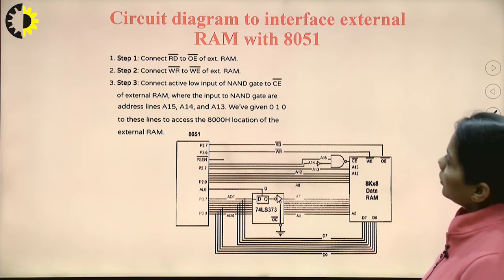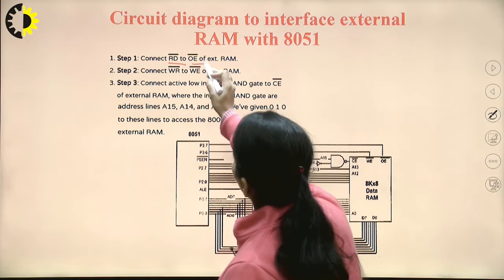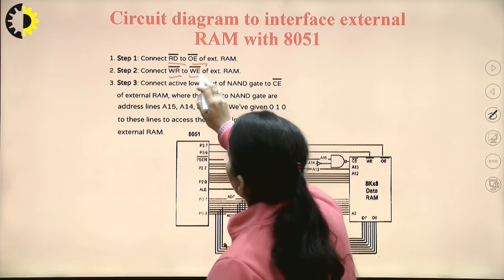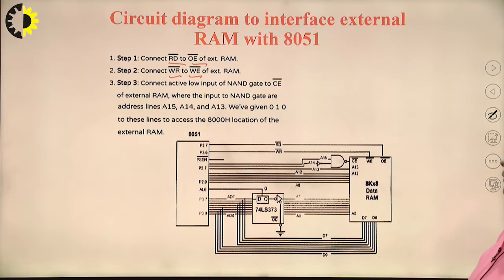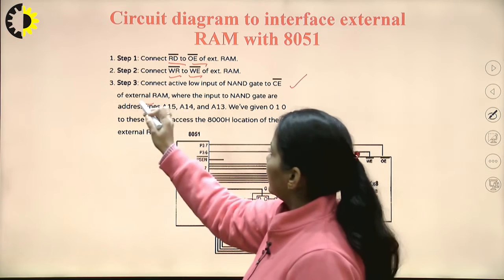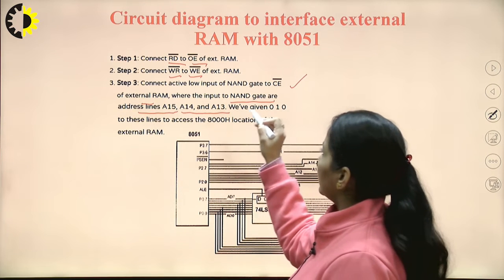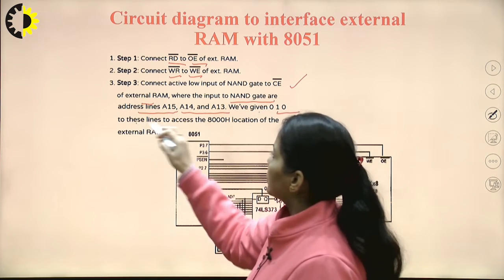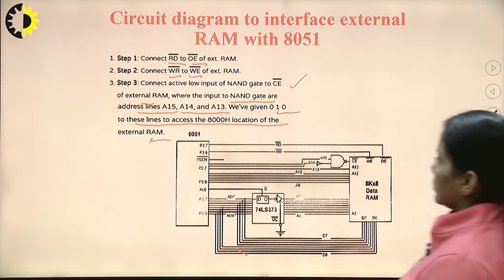Now, when we talk about this circuit diagram, we have to connect read to the OE of the external RAM, write to the WE of the external RAM, and connect the active low pin of the NAND gate output to the CE of external RAM, where the inputs of the NAND gates are address lines A15, A14 and A13. We have given 0, 1, 0 to these lines to access the 8000 location of the external RAM.